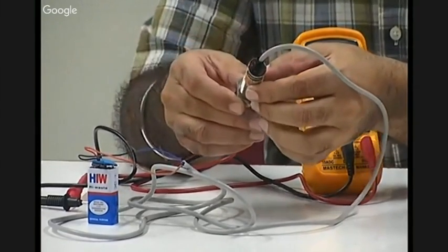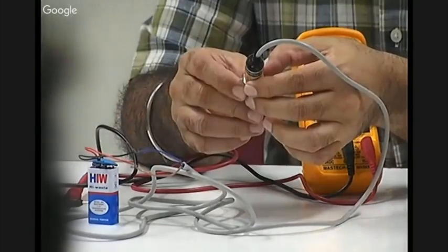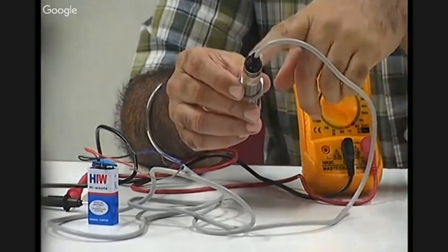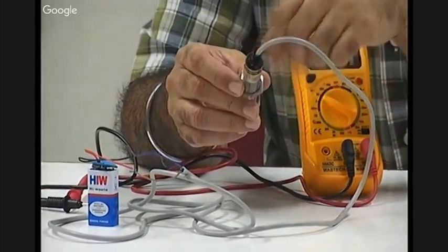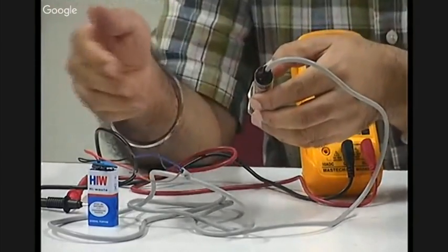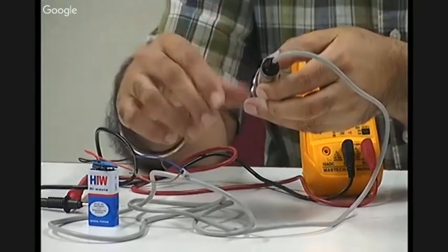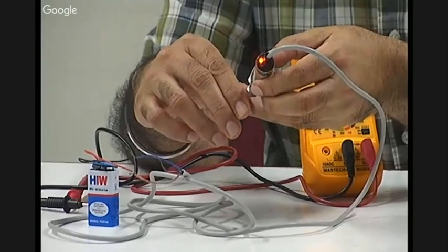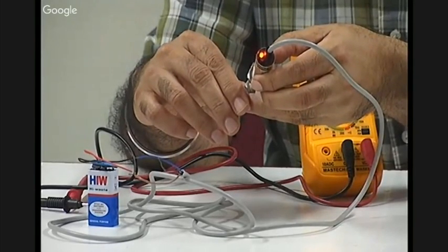So this sensor says that it has a range of 8 millimeter, but it requires 10 to 30 volt DC. It is written on this. We are supplying it a lesser voltage, so we may not be able to work up to 8 mm, but it's working up to say around 2 mm or so.